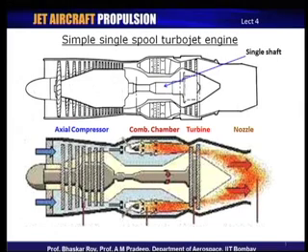So, in an axial compressor, or a compressor, the compression is performed. The flow, or the working medium, goes into a different space where the combustion is performed. Then it moves on to another space where the turbine extracts work, essentially to run the compressor, and then after the turbine has done its work, the working medium, now a hot gas, is exhausted through a nozzle.